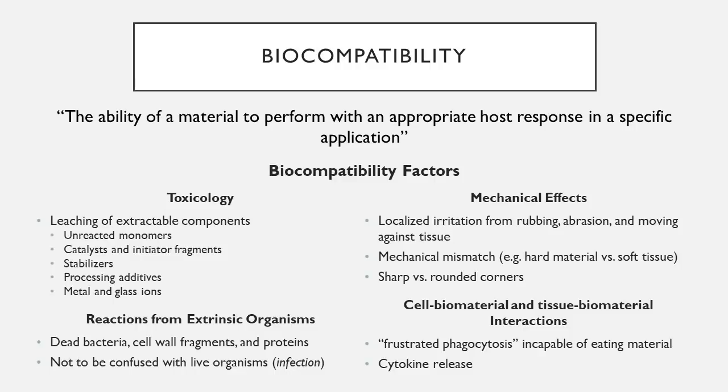So to provide a little bit better introduction to biocompatibility, I'll talk about four main factors that perhaps could make something bioincompatible. The first one being the toxicology of a particular device. Now, it seems obvious that a biomedical engineer would use non-toxic materials for a particular implant or biomaterial device, but that's actually not the concern of either the engineer or the FDA. What is a concern is some of the leachable extracts that remain within a polymer or metal, usually left over from the fabrication or storage process, that could potentially cause problems. These might be unreacted monomers for a polymer implant, catalysts or initiating fragments, stabilizers, process additives, or any metal and glass ions or fragments left over from the bulk of a material.